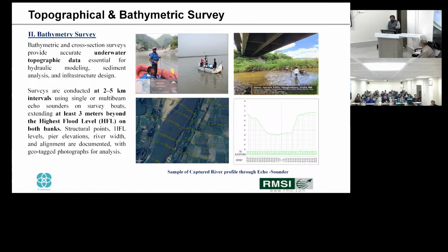So this is a bathy survey we have conducted. An underwater survey, because when you have a topographic feature from the LiDAR, from the aircraft, LiDAR cannot penetrate water. The LiDAR frequency we operate is an infrared range LiDAR. The water absorbs the infrared. So you will not get any return from the water.